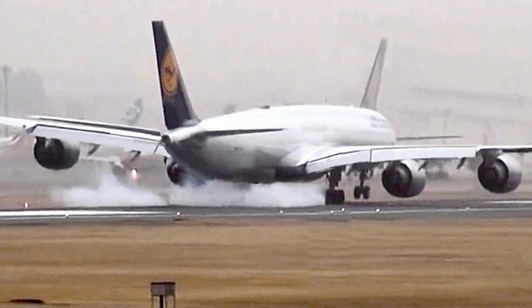Hard landing. When the airplane contacts the ground during landings, its vertical speed is instantly reduced to zero. Unless provisions are made to slow this vertical speed and cushion the impact of touchdown, the force of contact with the ground could cause structural damage to the airplane. The purpose of pneumatic tires, shock-absorbing landing gear, and other devices is to cushion the impact and to increase the time in which the airplane's vertical descent is stopped. The importance of this cushion may be understood from the computation that a 6-inch free fall on landing is roughly equal to a 340 fpm descent. Within a fraction of a second, the airplane gets slowed from this rate of vertical descent to zero without damage.